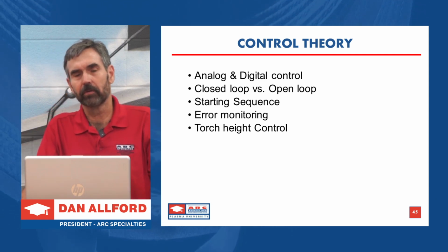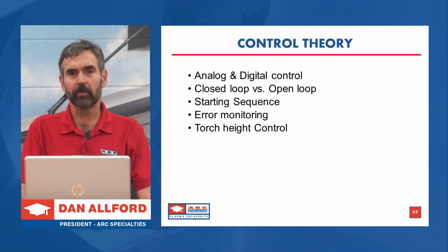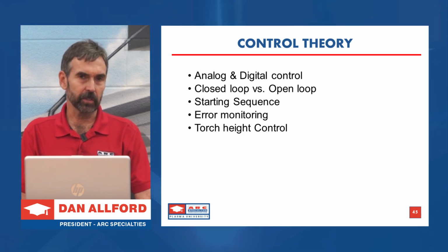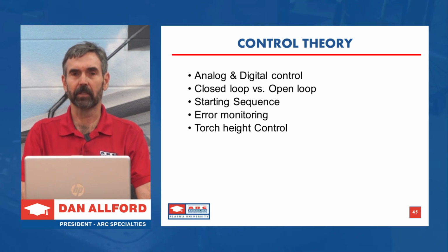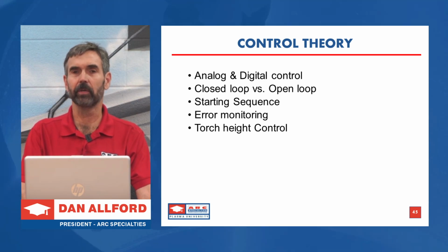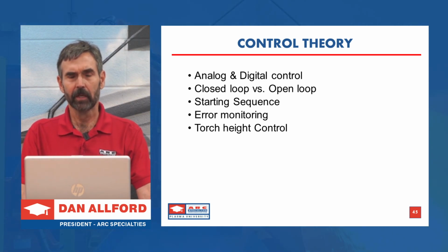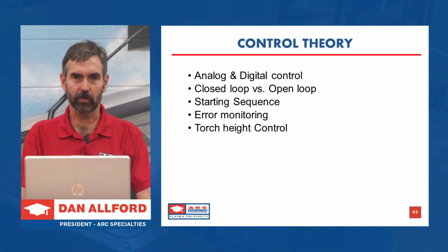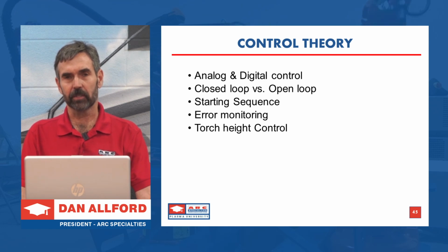So the first thing when we try to initiate the arc is we've probably already struck the pilot arc earlier. So typically on a plasma machine, the pilot arc is left running all through the day while the machine is up. And so the starting sequence on the pilot arc is first we turn on the pilot arc power supply. And once we see the open circuit voltage for the pilot arc power supply, then we initiate the arc with high frequency. So see, it's actually 2 power supplies used to make the pilot arc. And then we control that pilot arc as a function of current. Now we don't have to concern ourselves with voltage because the distance between the tungsten and the anode is always constant. So we simply let that run closed loop, monitoring the current alone. So that's how the pilot arc's running.